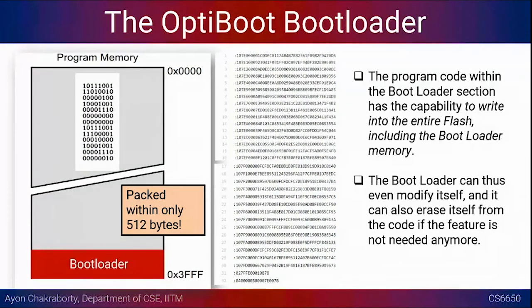If you look at the manual, it says the program code within the bootloader section has the capability to write the entire flash, including the bootloader memory. So this is such an intelligent program, right? It is going to eat itself up, and it's going to expand the space for writing application memory. That's why we are saying read-while-write. So it's reading and writing, and it might happen that once the entire thing has been written, the bootloader is non-existent. The bootloader is gone. Okay, so that much intelligence could be packed inside the bootloader.